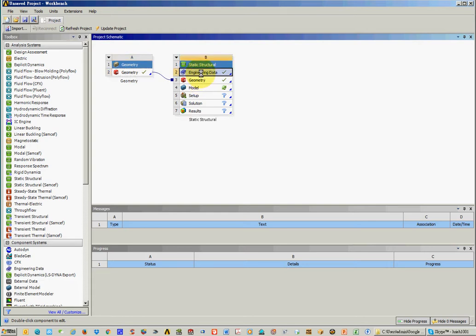The second step would be material, and the third is meshing the model. Step 4 will be boundary conditions and loading. Step 5, running the solution. Step 6, the result. So we finish the first step, which is drawing a 3D model in a CAD system and feeding the CAD model into ANSYS.